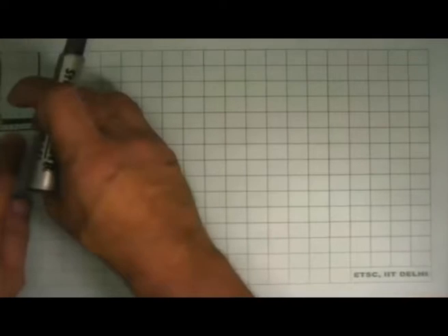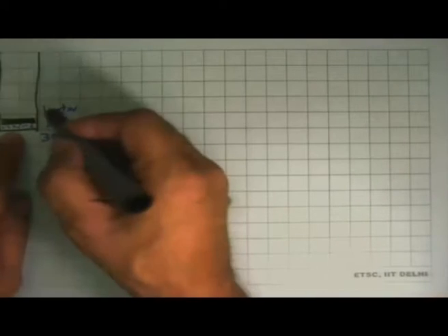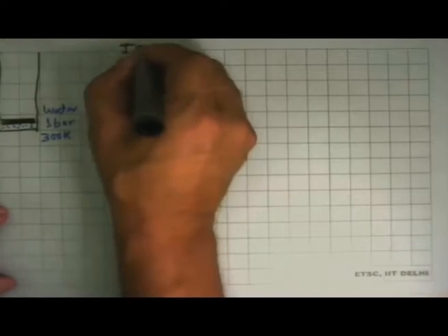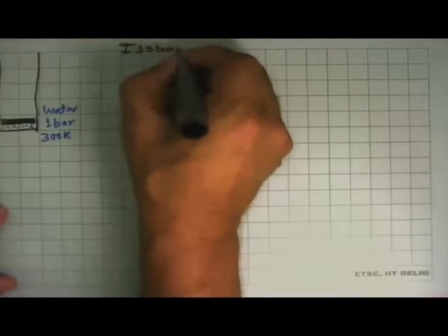Heating it, sometime will stop so that there is equilibrium, and then ask the question, the pressure I'm going to keep as 1 bar, what is the temperature? That's the first question. The second question is, what is the state of the substance or the state of water inside this? So what we are doing now is what we call isobaric heating.